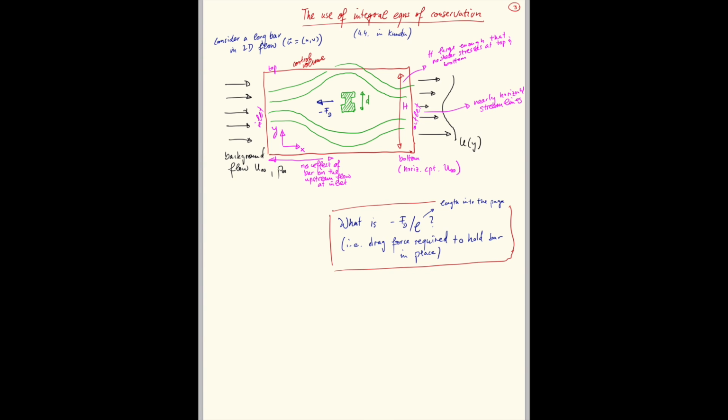So let's write our mass conservation equation. Number one, mass conservation is d by dt of the integral over the control volume V*, plus the integral over the control volume's surface area of rho (u minus b) dot n dA, equals 0.